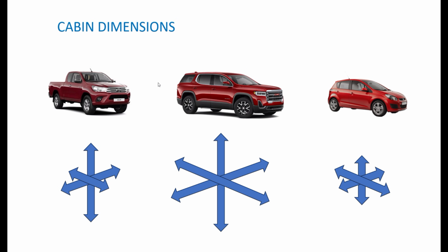Where you locate your speakers relative to the driving position, how far those speakers are away, how they're aimed, where you've actually located them, whether they're on the pillars or on the dash or in the kicks. All of these things will affect the reflections, the cancellation, comb filtering, standing waves, cabin gain, all of these types of things, and what we call the cabin response of your particular car.